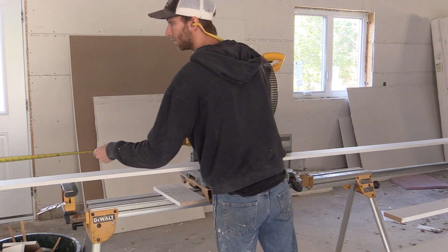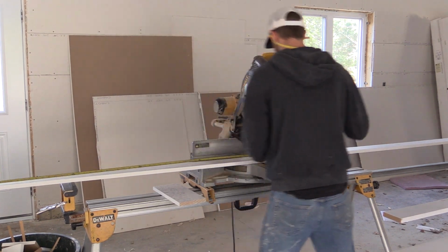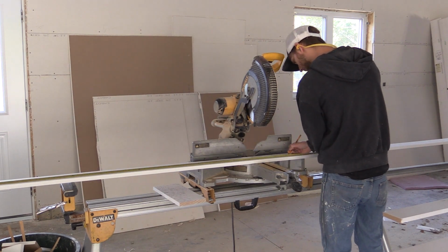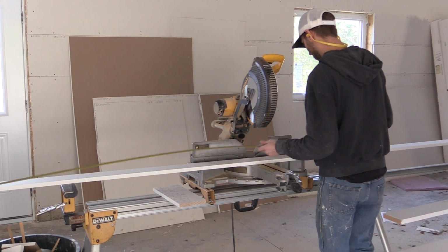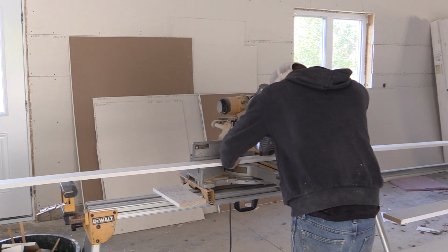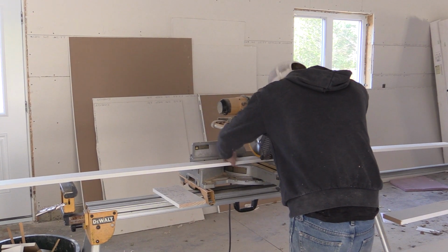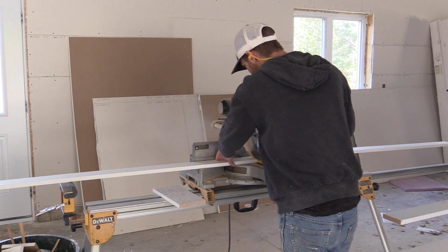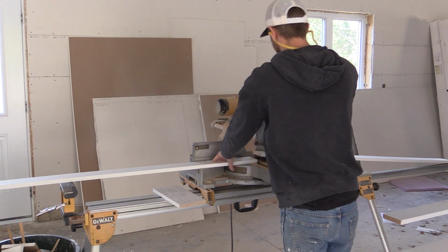The carpenter transfers the measurement to a piece of the trim board, being very careful to mark it with a pencil at exactly 46 5/8 of an inch. He then cuts the board, making sure the blade of the saw is in the right place to leave the board exactly the right length. This level of precision in measurement ensures that the finished product looks perfect.